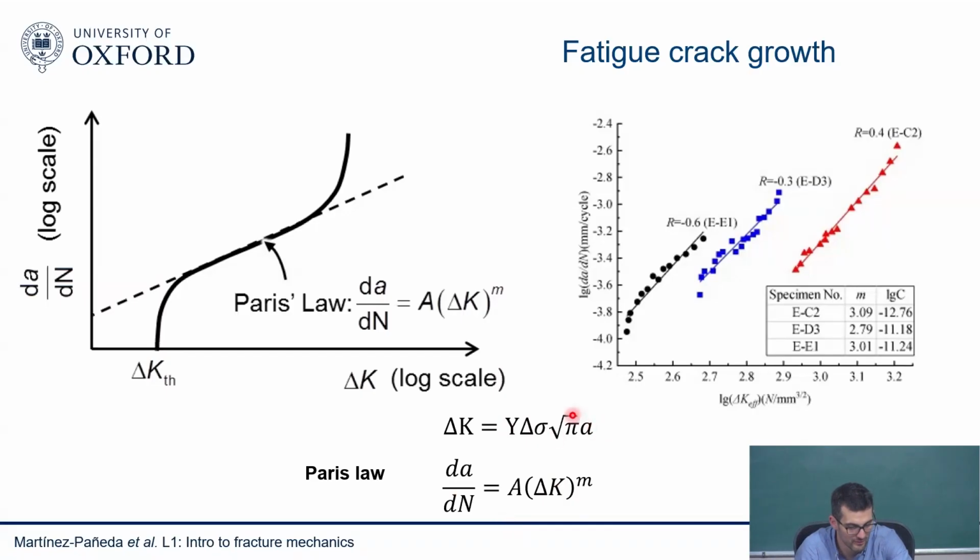So yeah, the square root of A goes here, the A goes this way. You put everything related to A on one side, number of cycles on the other. You have everything. The only thing that you're missing in this integral is the number of cycles at which your crack becomes 5 millimeters. So you solve that integral, you put in the numbers, and you end up saying, after 3,400 cycles, you get a crack size of 5 millimeters. So they will say, we get 2 cycles of load every time we fly, because it's one to go up and then down. So that will mean after 2,000 flights, let's go and check my crack, how it is. And we expect that we will have to change it every 2,000 flights.